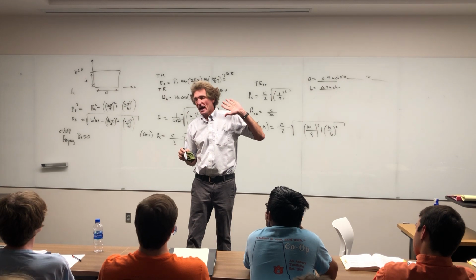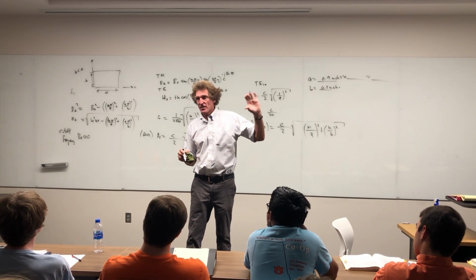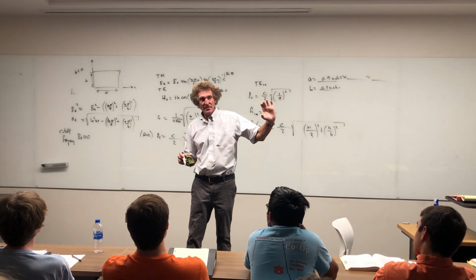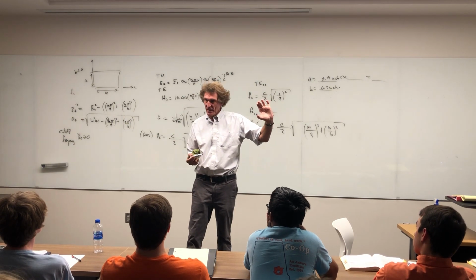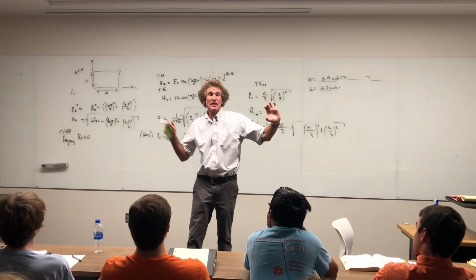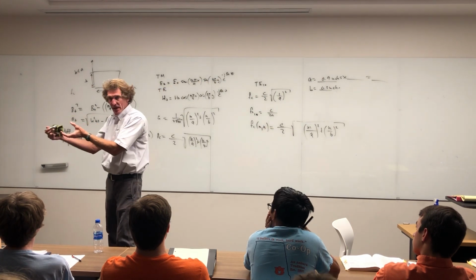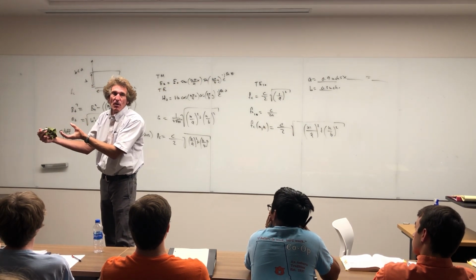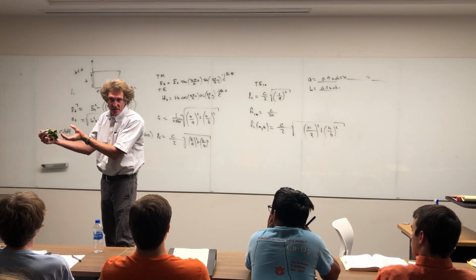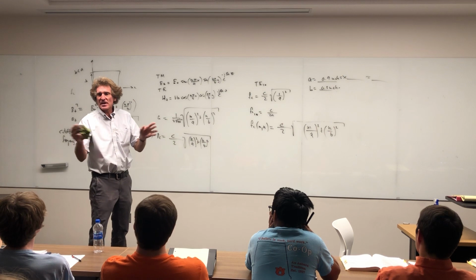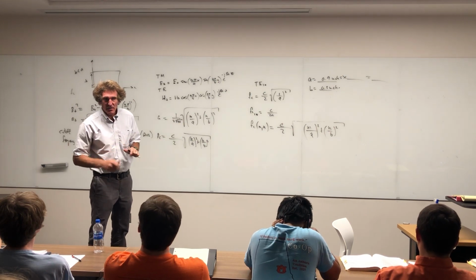What really happens most of the time is that you have an antenna and they make sure the driving point impedance of that antenna is the same as the waveguide. Follow me? Or if you have an amplifier that you're plugging in, it will have the same output impedance as the waveguide, so it's impedance matched. I'll show you how they drive these things in a bit. But just realize it's just like transmission line, baby, all right?